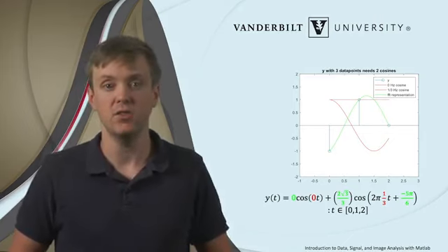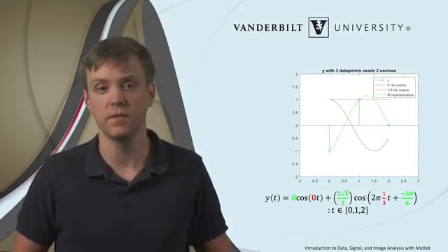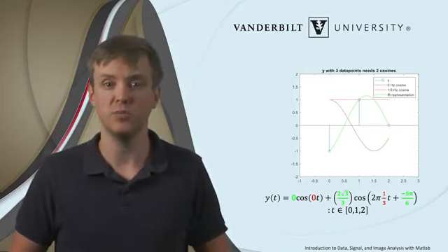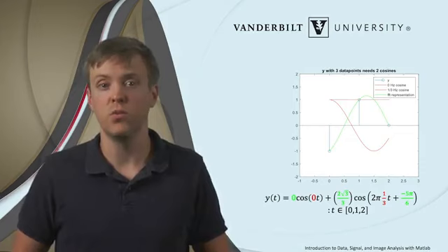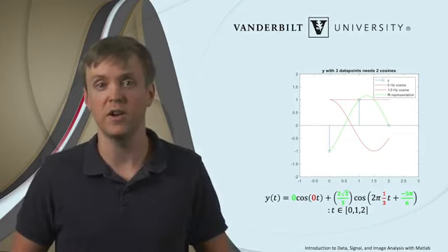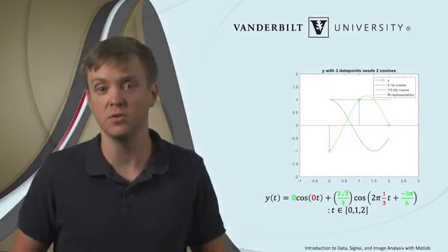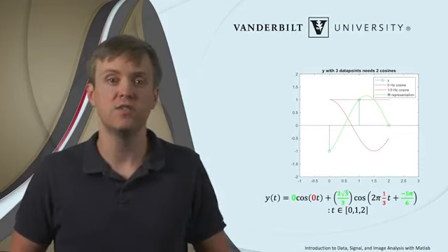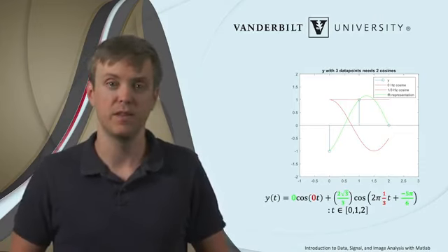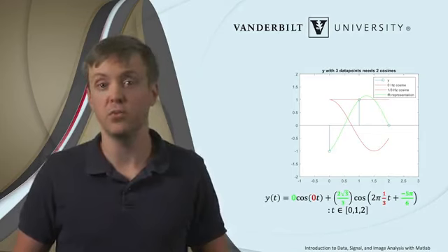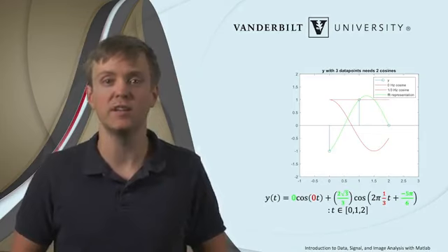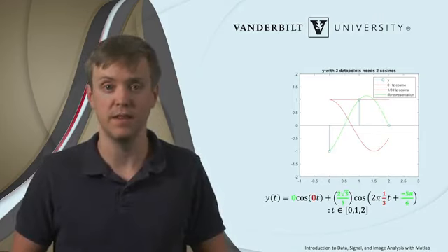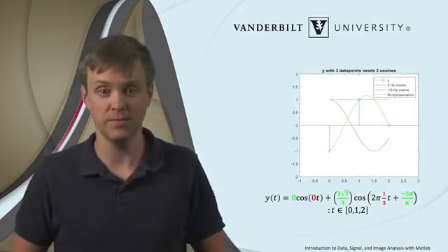Then we have the magnitude and phase of our second cosine. So in total, our IFFT needs to compute 3 numbers to represent our signal as a sum of cosines. In summary, with y, we have 3 data points, and our IFFT needs to compute 3 unknowns. This should sound familiar from linear algebra. When solving a linear system of 3 equations and 3 unknowns, the linear system is fully determined and we can compute an exact answer. This is precisely what's going on here.